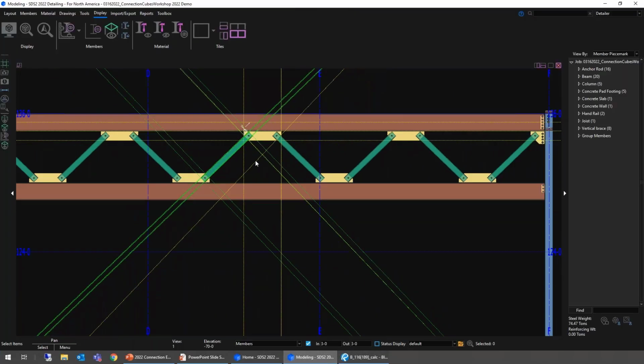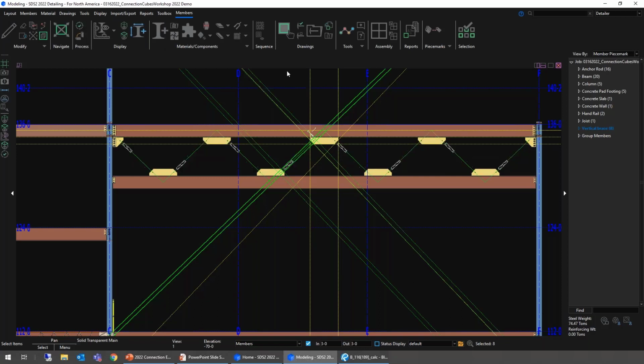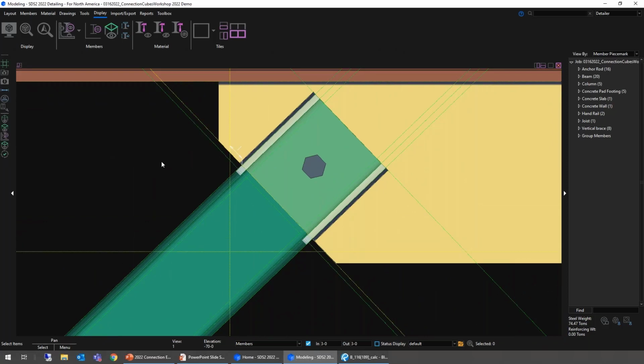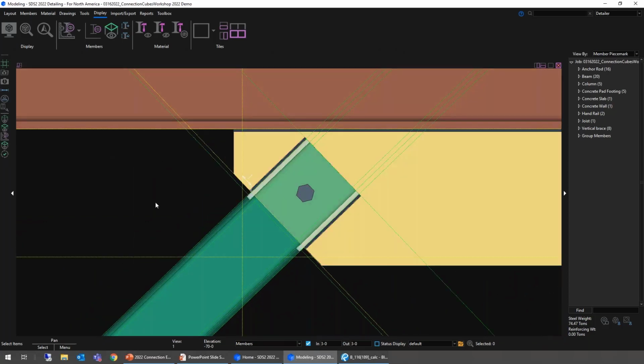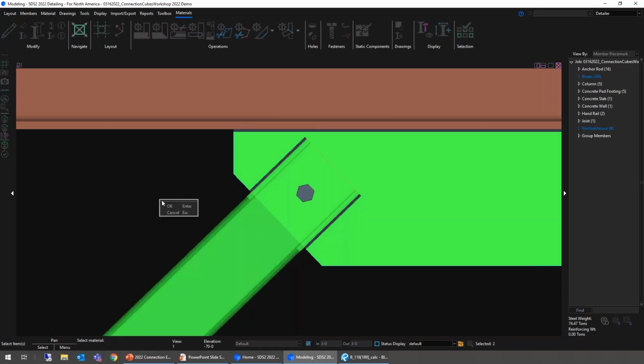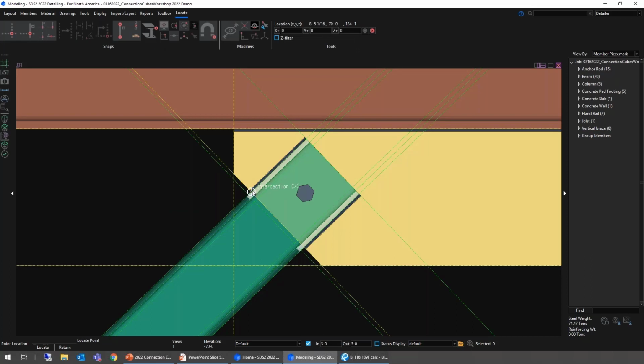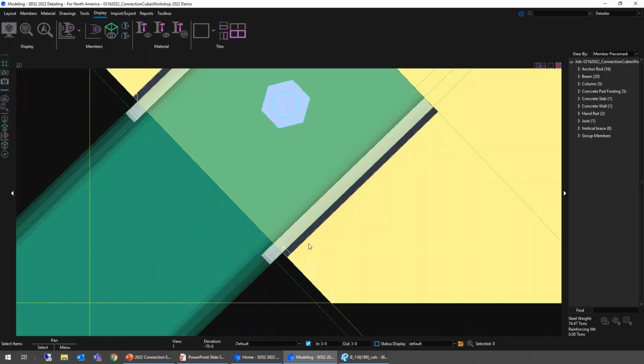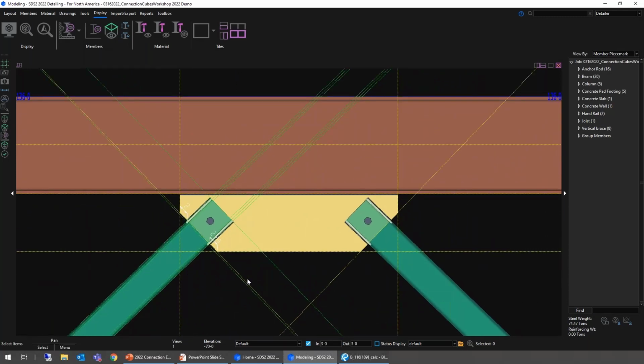Okay, I'll come in here. I'll just update maybe all of those braces for us here. Okay, so we can see already my construction lines are off. My dimension is off here. So let me get rid of those. And that dimension, I'll go ahead and re-add just to verify and prove what we're seeing there. So now we've got 2 inches as the minimum here. I can measure that other side here, and we're going to see that as well. 2 1/16, probably a slight rounding issue going on there. But we can see we're getting that minimum 2 inches.